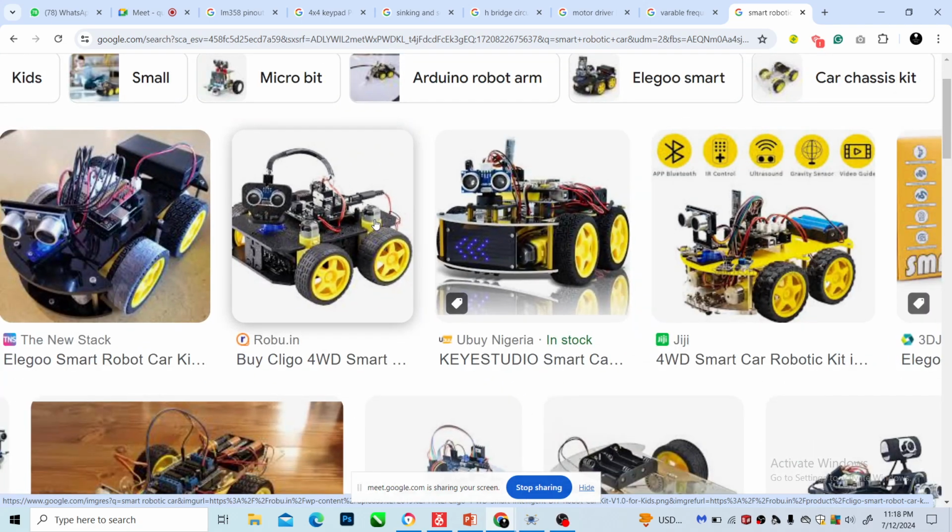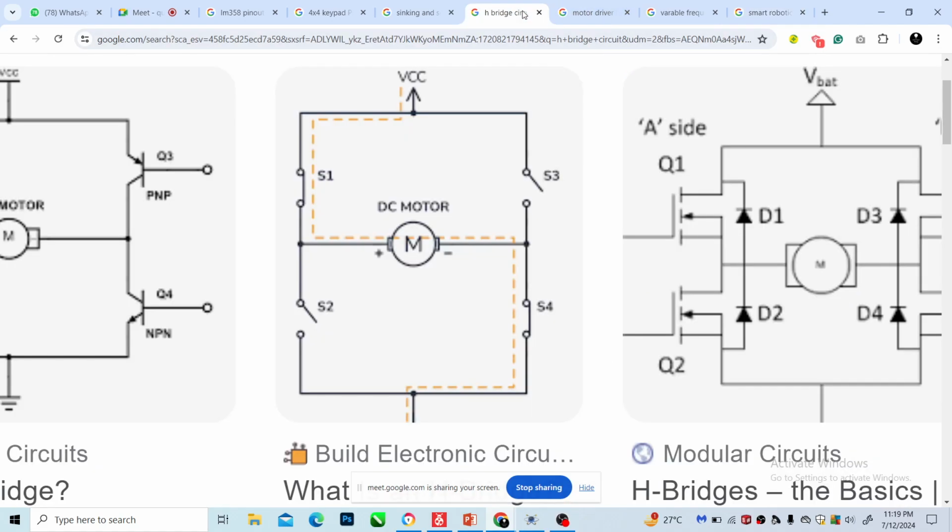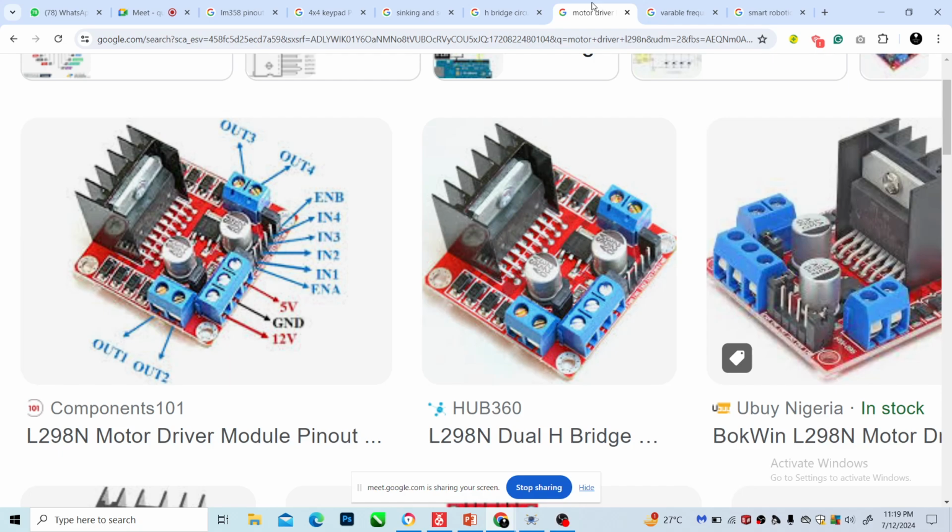So when you join them, how do you do that? You can take a small battery, test this one, take another small battery, test this one. So red goes to red, black goes to black. Do you understand? Then you feed that one side to one H-bridge. Are you with me? Then you connect the other 2 ends like that, and you feed them to the other H-bridge. That's the reason why they put 2 H-bridges inside the motor driver, because they know that you need 2 H-bridges to achieve this. So there's no motor driver you will find that has one single H-bridge. It's 2 H-bridges.